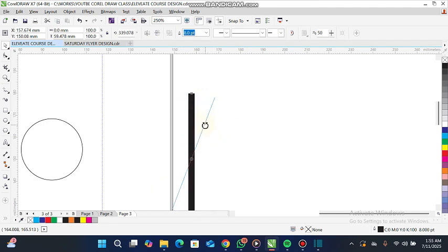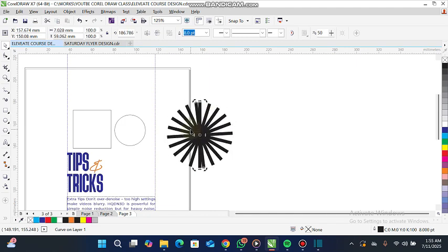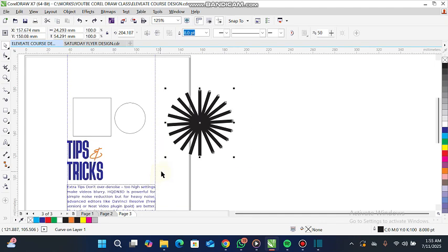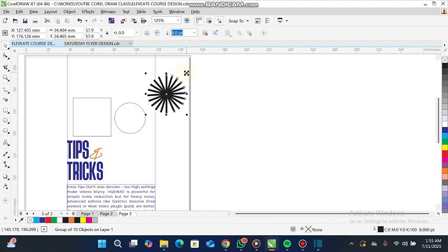I want it to go in the right direction, and I will right click whenever I'm okay with the point it is. I have duplicated it. All I have to do now is Control R on my keyboard to duplicate it the way I want. As simple as this. This is how we manipulate and create images or shapes faster in CorelDRAW.